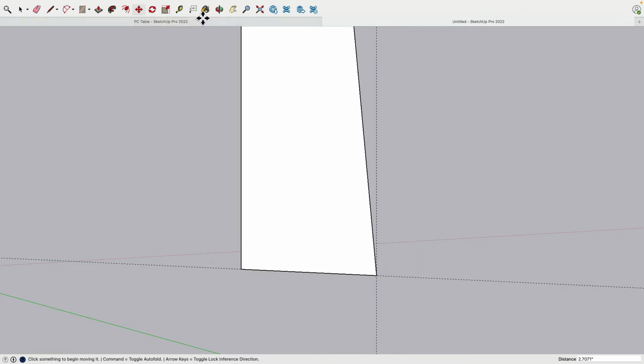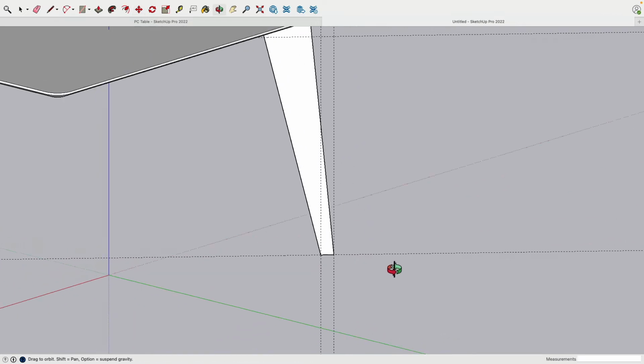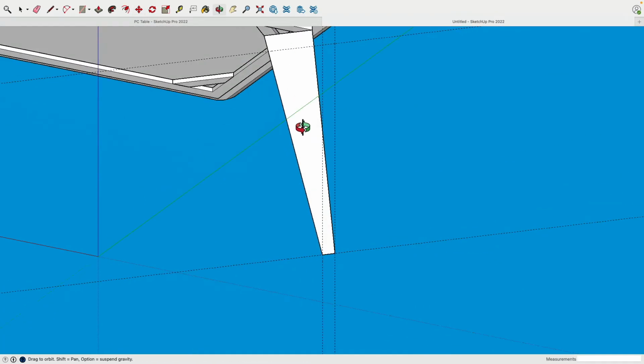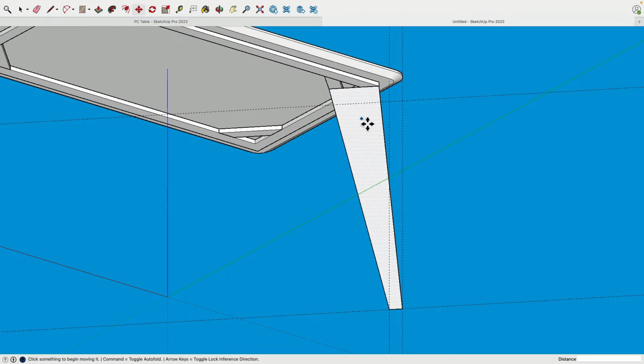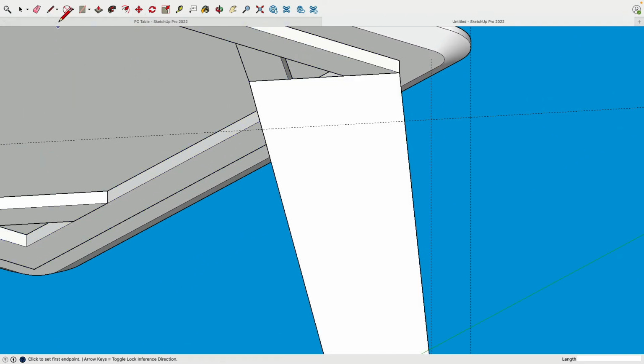And now from here backwards, that should be 1.5 inches. Now I have another snap point. So this end point of the line goes to there. This way, as you can see, I also maintain that this surface remains totally flat. Cool. Okay. I can draft a line down there and a line maybe to there. And then this here I will erase.